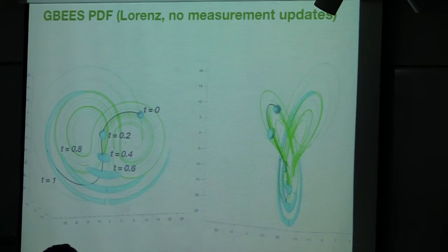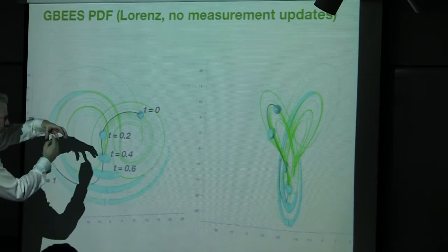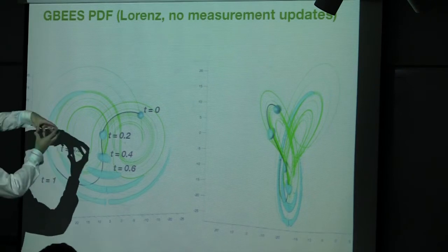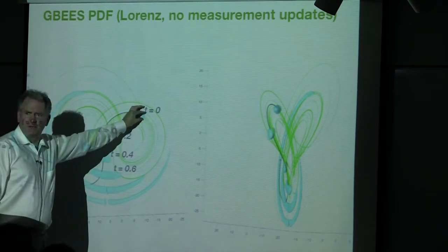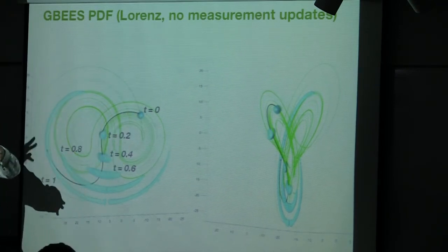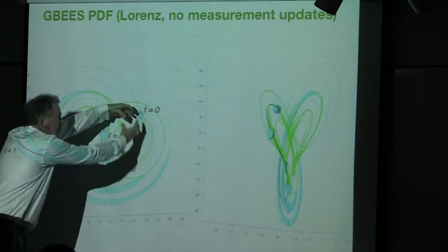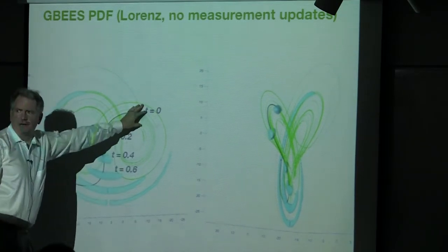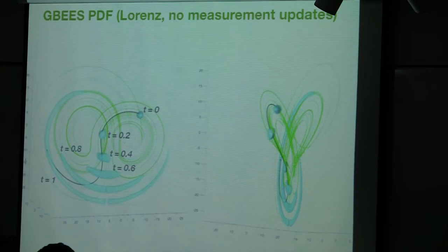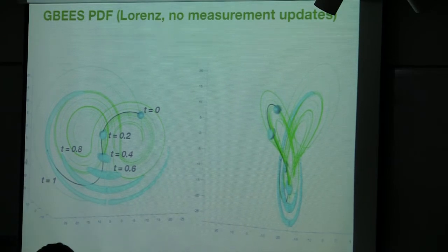The eigenvalues are how big that football is in each of the 3 directions, and the eigenvectors are the direction of that football. So that covariance matrix is a 3x3 matrix, has 3 eigenvalues, 3 eigenvectors, and describes a football of uncertainty around that point, if we describe it in a Gaussian way. And if I were using a Kalman filter, or in the nonlinear case an extended Kalman representation, I'd restrict my description of that ball of uncertainty to continue to be a football.